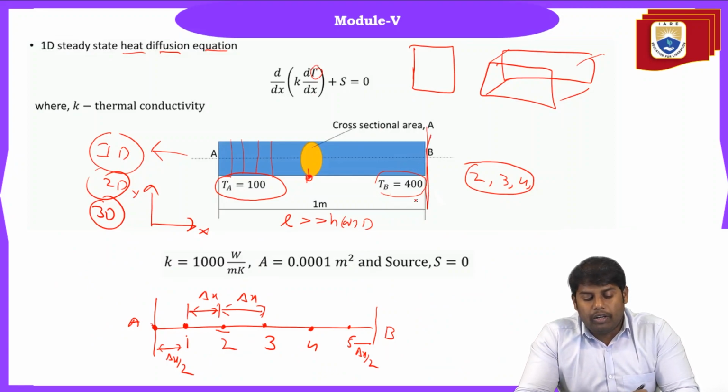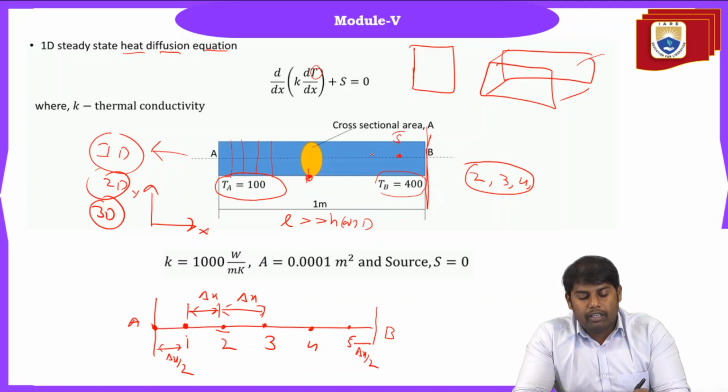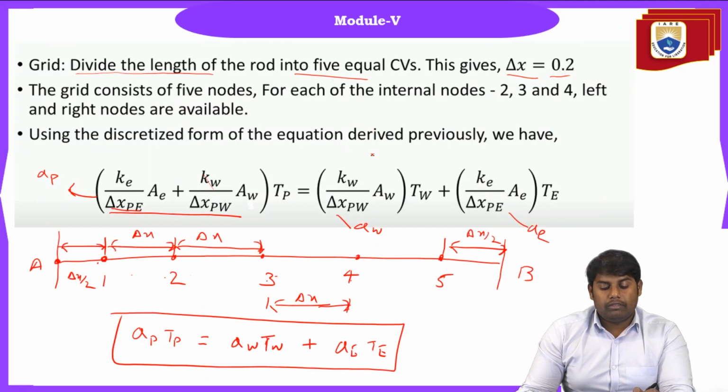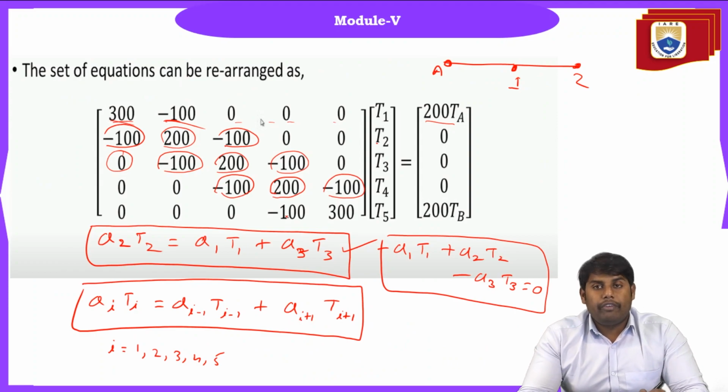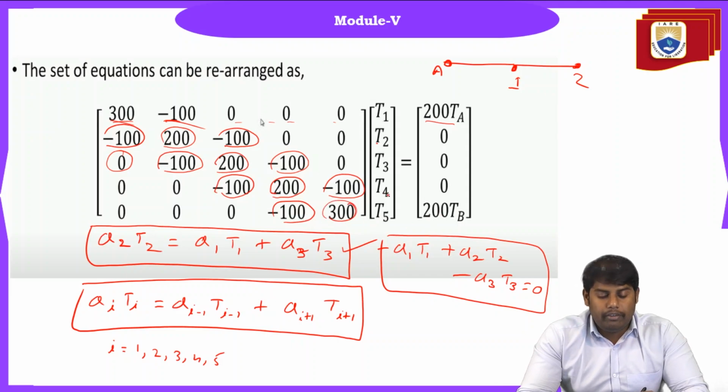For the fifth one, so we have a wall here. Fine. So when you take the grid point 5 here, so for the right boundary, we apply a temperature boundary condition here. Fine. So when you take the fourth one, it is the neighboring point. So this is what we have. So point of interest, the left one, point of interest, and the right boundary, we have a source term which is 200 to be. So what is happening when we have walls?